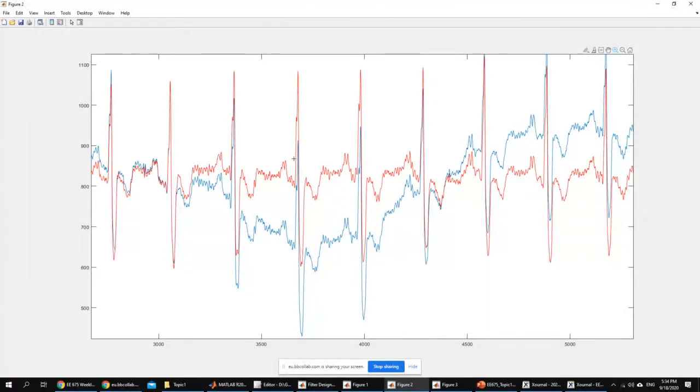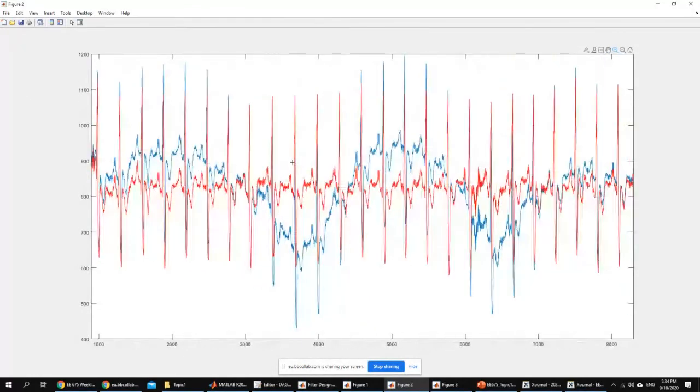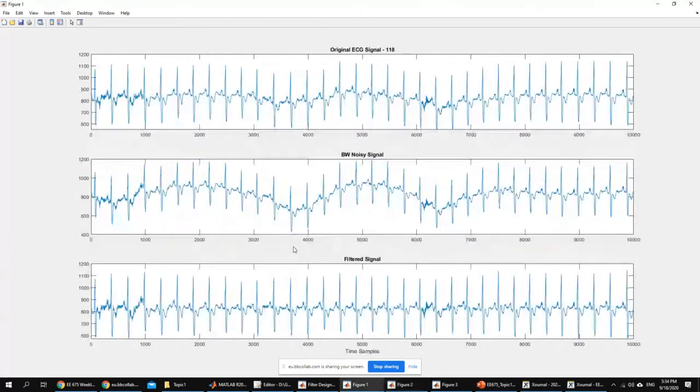So the use of filter, as you see here, gives you something that is really clean. It looks very nice from the beginning to the end of the signal. See, even that small part here is still present here, exactly the same. Perfectly aligned. So the use of zero phase filter is actually very good. It gives you something that doesn't have any transient, and doesn't have any group delay during the signal.